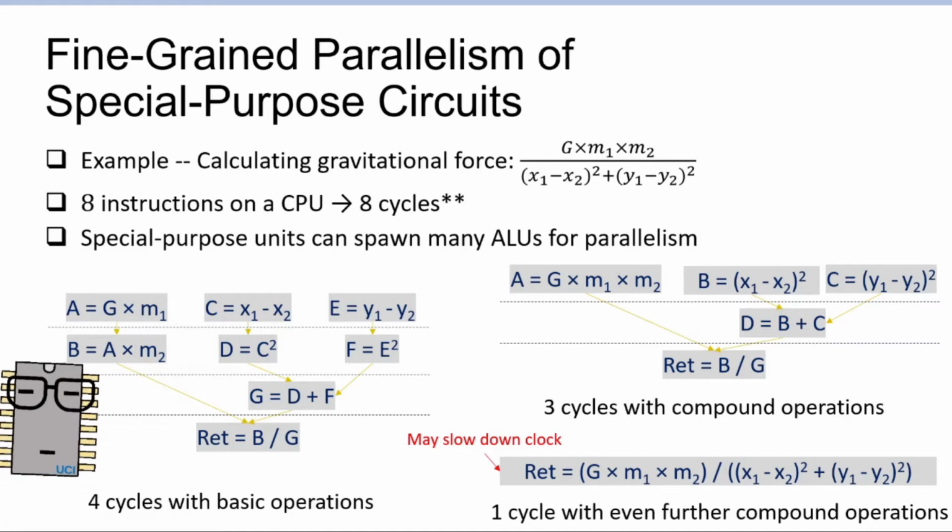So in terms of flops, floating point operations per second, compared to a single thread software, which is multiplexing 1 ALU, the performance of which will peak at 1 floating point operation per cycle, because we have 1 ALU, this design can be running 8 ALUs at any given time as long as there's data to process, giving us 8 flops per cycle, which is much better performance.